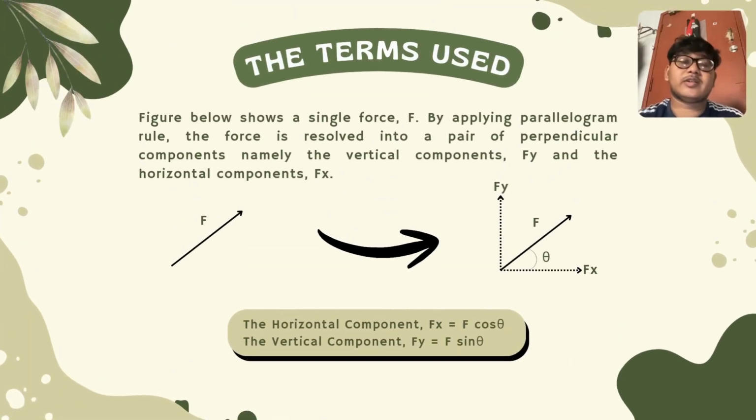Next, let's continue on how the terms are used in this topic. As we can see, the figure below shows a single force that can be defined as F. By applying the parallelogram rule, the force is resolved into a pair of perpendicular components, namely the vertical component Fy and the horizontal component Fx.